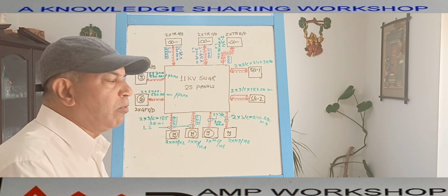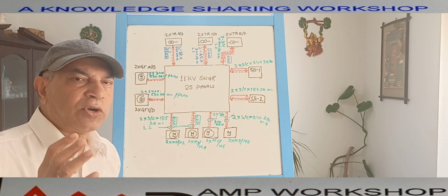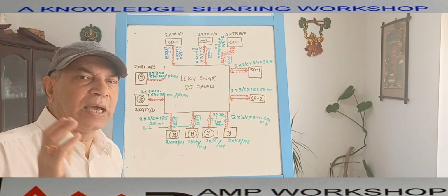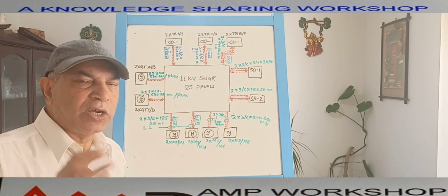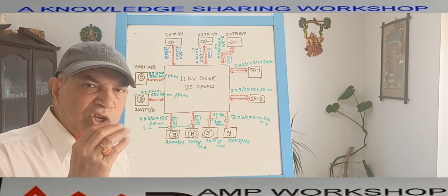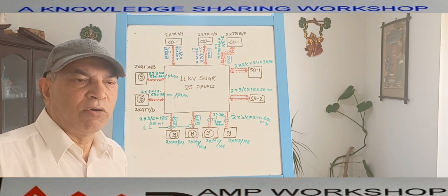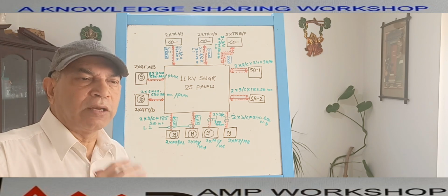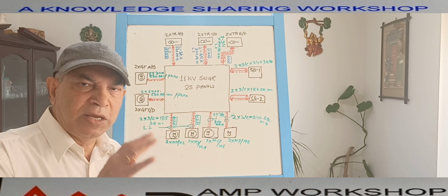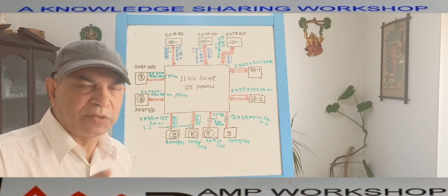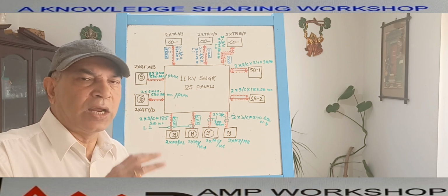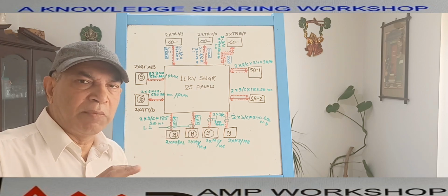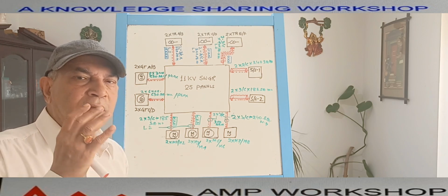Now, to produce the cable block diagram, we need some important reference document. What is that reference document? That is your cable sizing calculation. Now, the project has different phases. When the project is initiated in the conceptual stage or the front-end engineering stage, the company generally decides what plant equipment is required to start the plant, what the various loads and equipment are, what the tentative layout is, and what cables are required. That is also identified in the FEED documents.